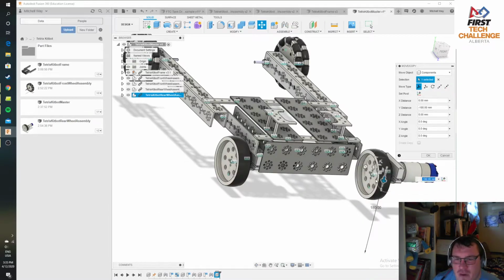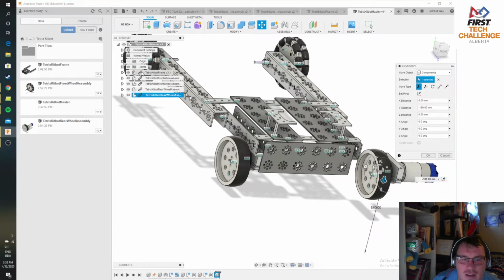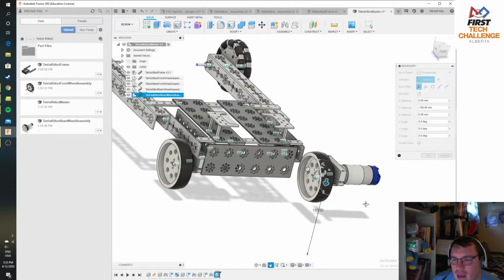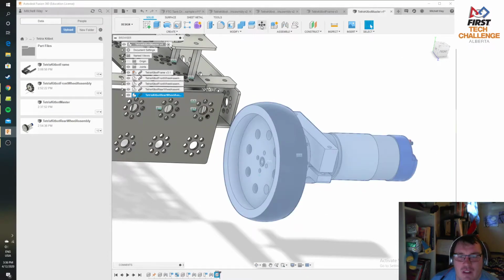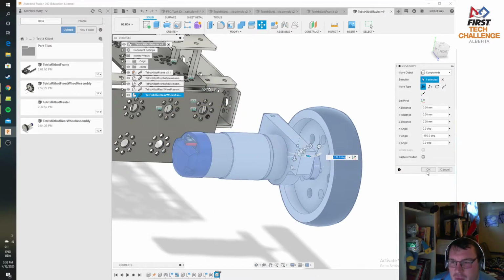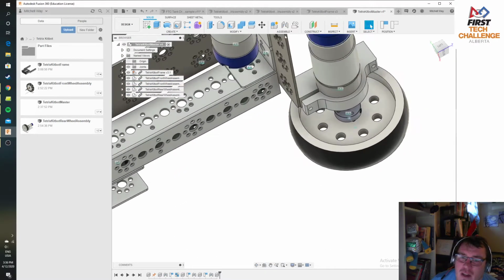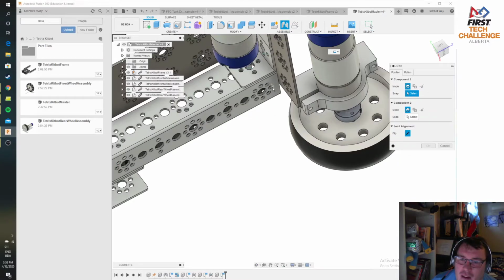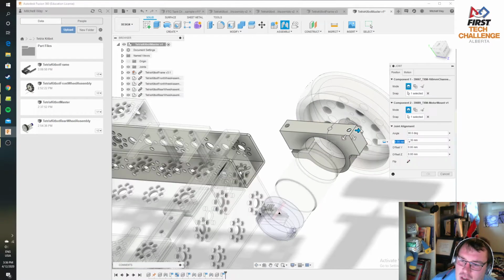And you'll notice in your browser, every time you do this, you simply get another set of components. Each of these could be opened up to show all of the components that are inside, but it is linked to the actual piece over here that shows where it came from. And again, I think we talked about that in a previous week, but this allows us to very easily, A, work with these pieces, but also B, modify them if we have to in a very easy way. And I'm just going to show you a quick example of that. If you've already seen it, I apologize, but it is one of the most powerful things about CAD that we use, period. Again, I'm just going to use a rigid joint, and I'm going to attach this piece to this piece here.